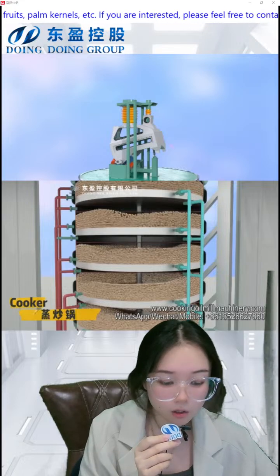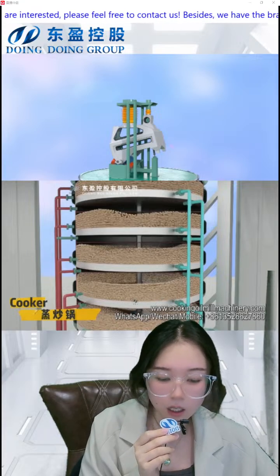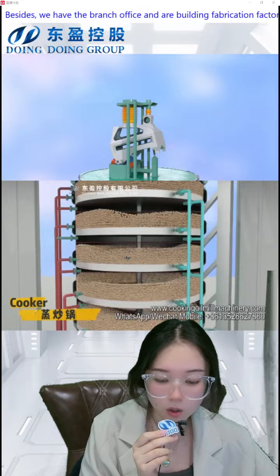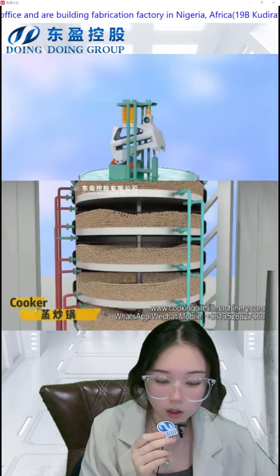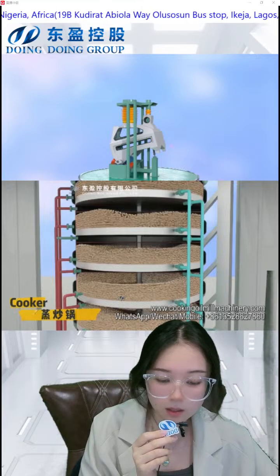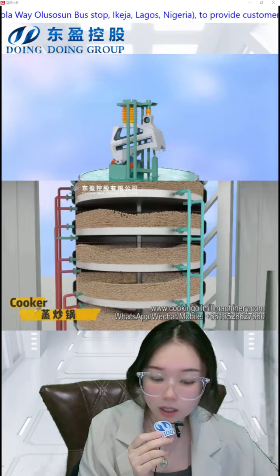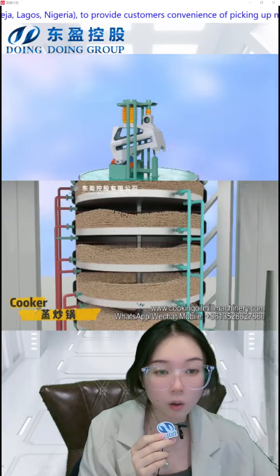Also, in order to steam and fry the soybean evenly, each layer has a stirring knife. There is an automatic feed door for the soybean to control the feeding in each single layer. The bottom layer of the cooker has an adjustable discharge door, so the steam cooker has a high degree of automation, and the steaming and frying effect is also good to help you get a good quality oil.